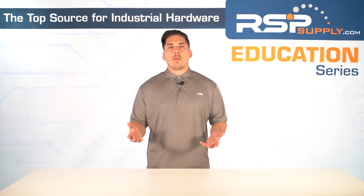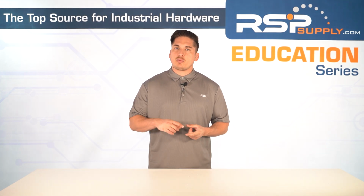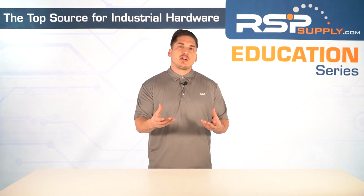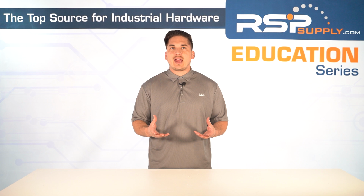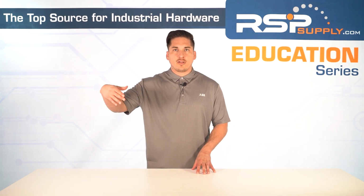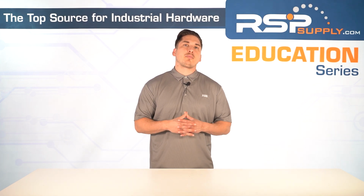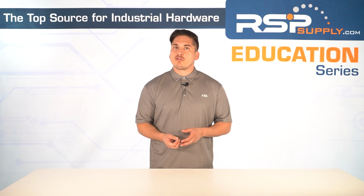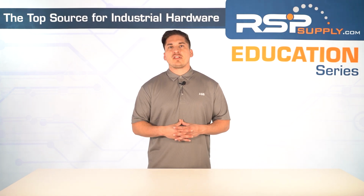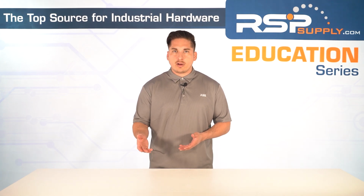All right, so let's recap. 4 to 20 milliamp is the backbone of process control because it's reliable, noise resistant, and great for long distances. 0 to 10 volt is simple and common in HVAC and building automation, but not ideal for longer runs since the voltage drops. Fieldbus protocols like Foundation Fieldbus and Profibus PA reduce wiring and allow two-way communication. HART gives you the best of both worlds, analog control with digital diagnostics layered on top.